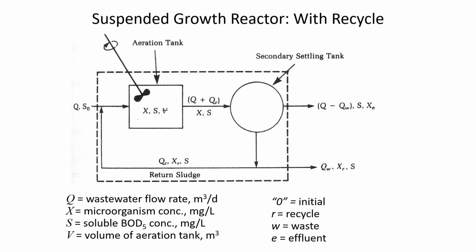And it's not actually sugar, it's any kind of food source, whether it's carbohydrate, fat, protein. They're taking the BOD, turning it into body mass, which can be settled. We couldn't settle it before they turned it into microorganisms. That's why we want them to take out the BOD, because we can settle microorganisms, but we can't settle dissolved BOD because it's dissolved.